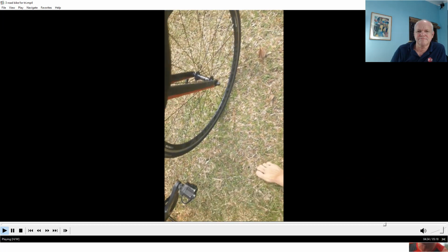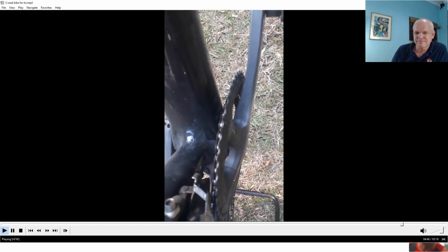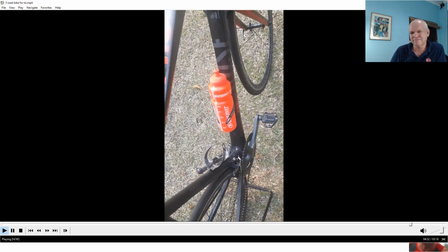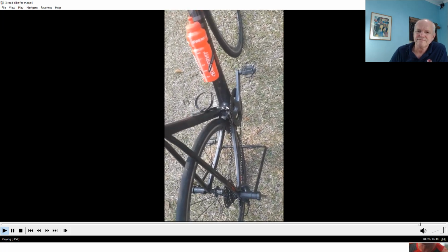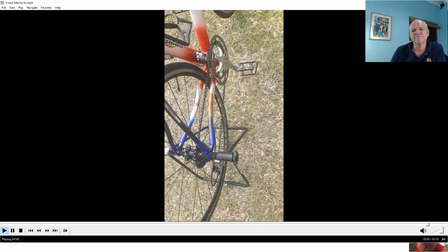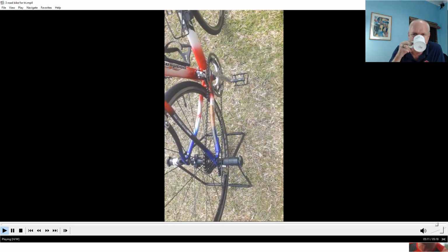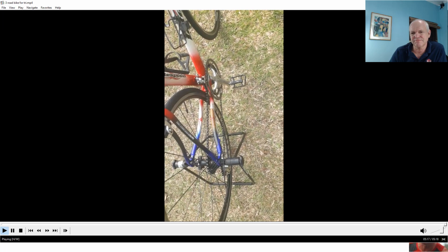And on my newer bike, here I have a smaller one, it is 34. I also recommend, especially for beginners, use the 34. So if you have in front 34 and in the back 32 or 34, then you have almost 1-to-1 between the front and the last one. And it is much easier to go up the mountains compared to this one, where you have 39 to 25, and in the lowest gear you have to really fight up the mountains because it is very, very heavy and difficult to go up.